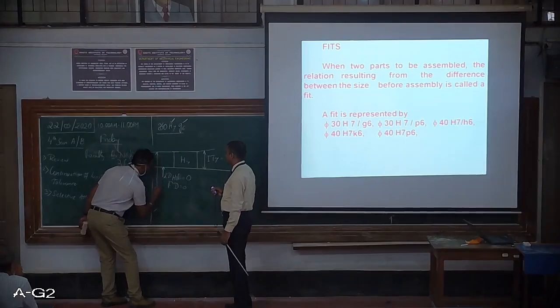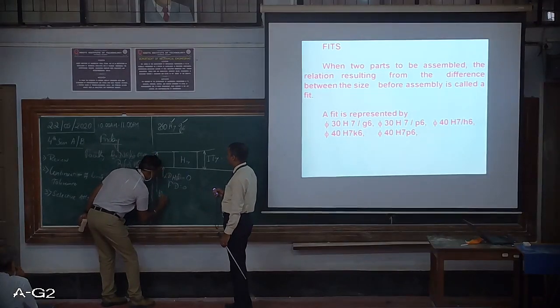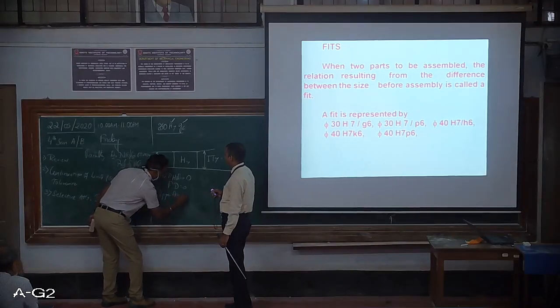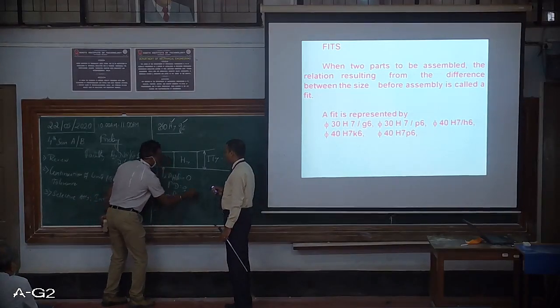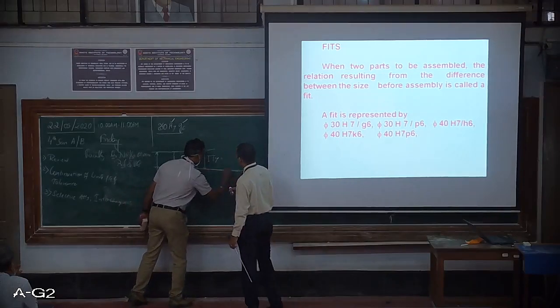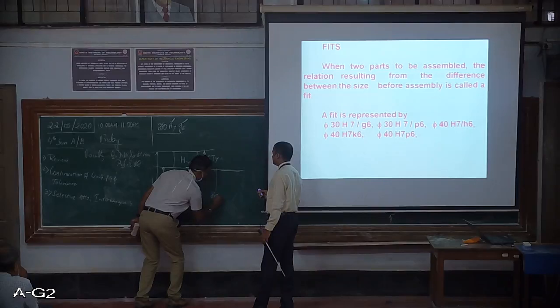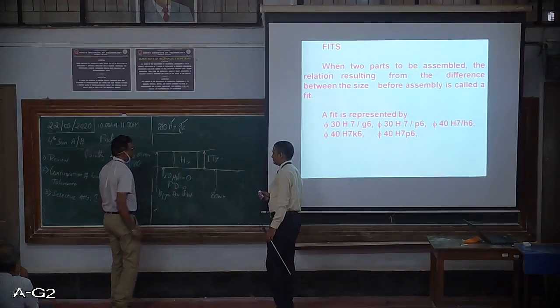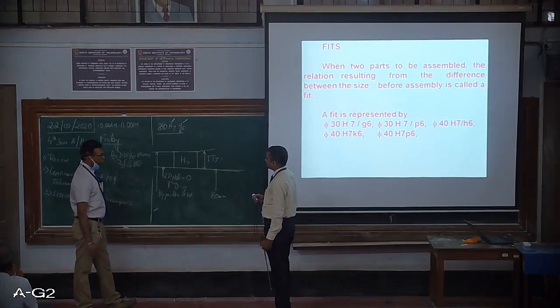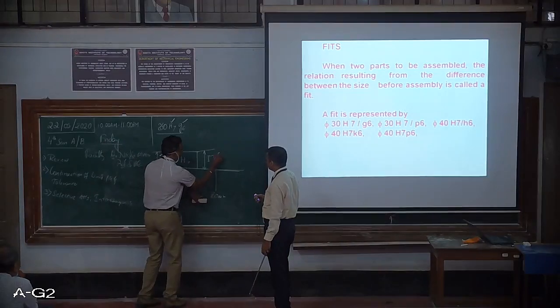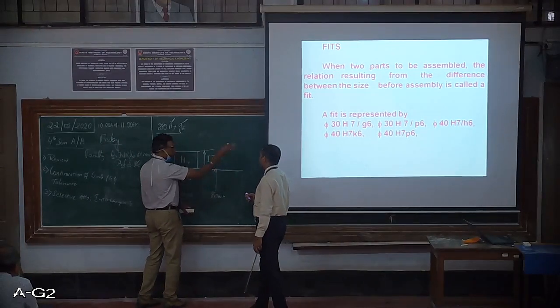Then this is the upper deviation of the hole. Okay. Next, this is the nominal size, which is 30 mm. So this is with respect to the H7 hole. Once we get this, we should be able to find out how much is IT7, and that is further.